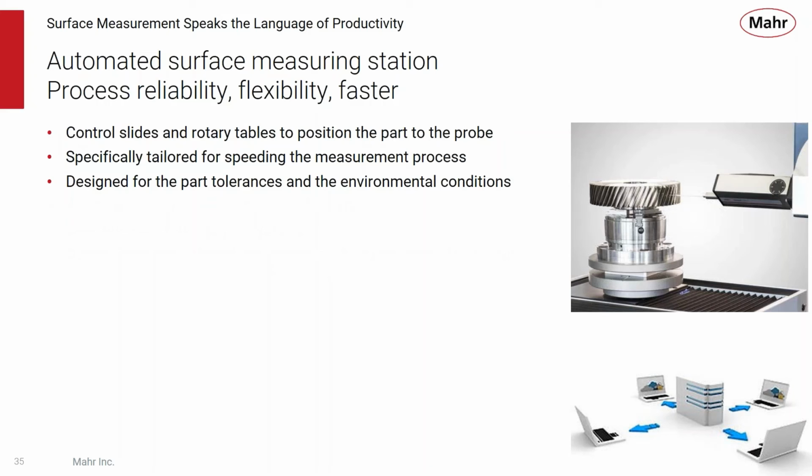Within these gauges, there are slides and rotary tables to help position the part to the probe. They're specifically tailored for speeding the measurement process, and they're designed for part tolerance and the environmental conditions. So they can have enclosures, vibration pads, and so forth to ensure that they work well at the point of manufacture.